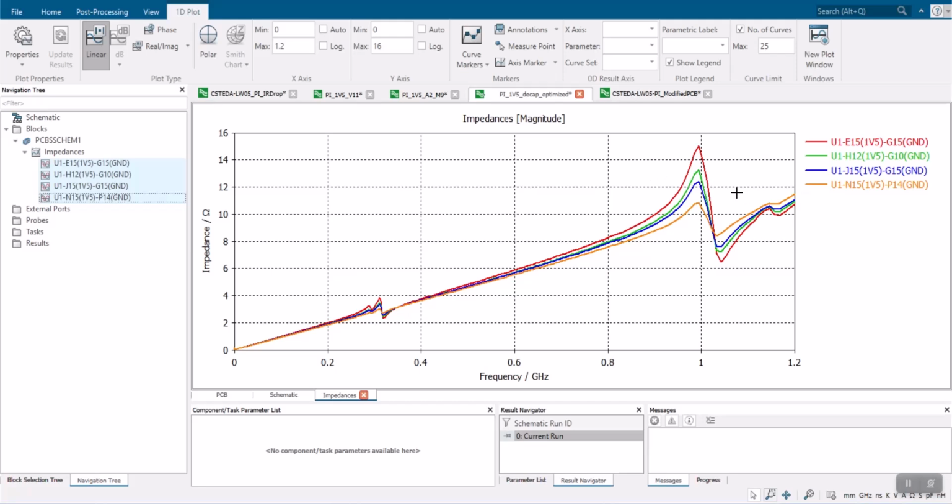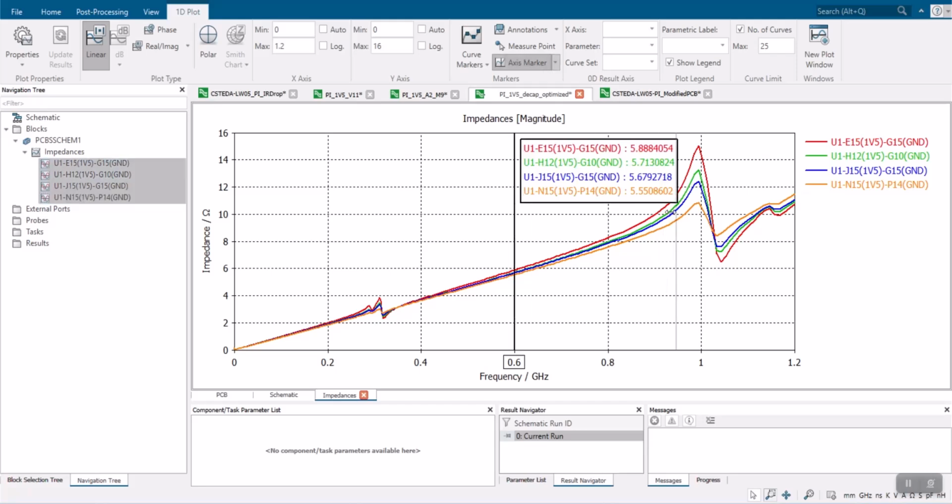We can see for the new result, at lower frequency there is almost no resonance. There is only one resonance frequency, almost 992. Actually, except for the 1D plot, we can check the 2D or 3D plot in CST.